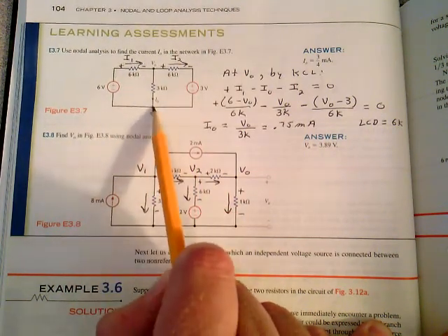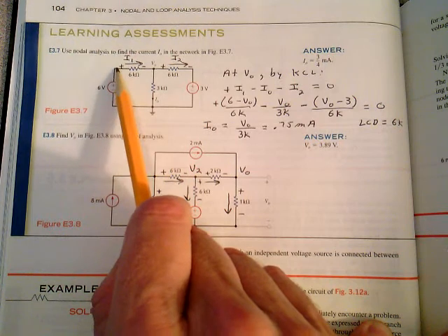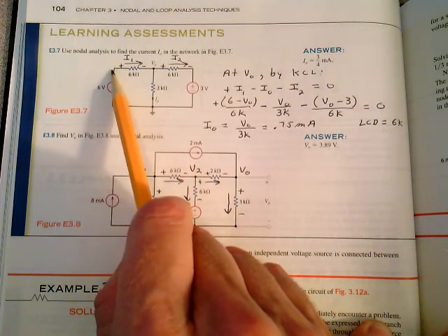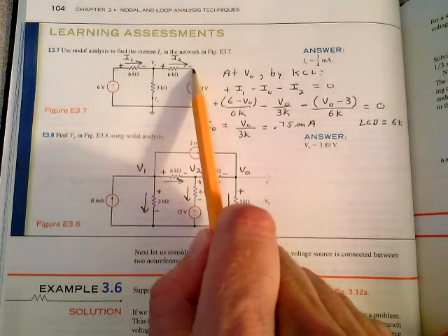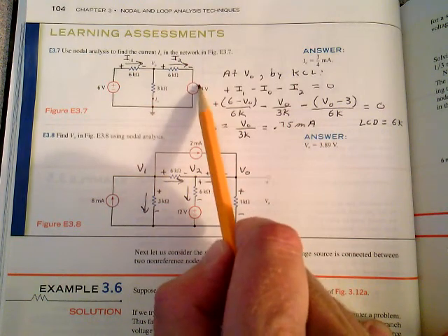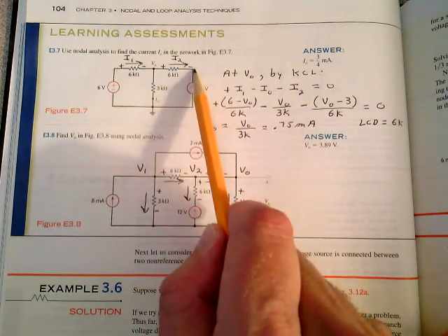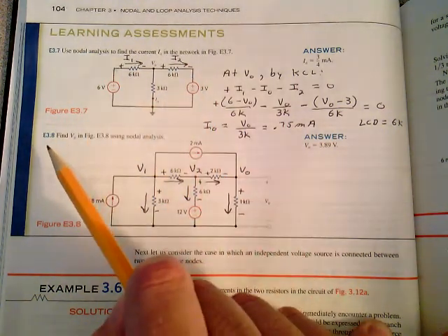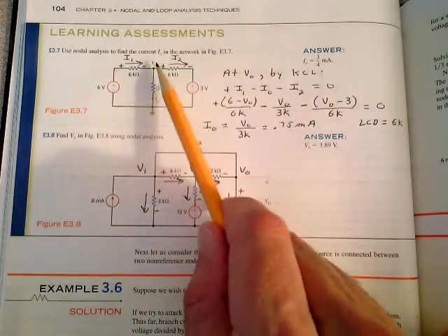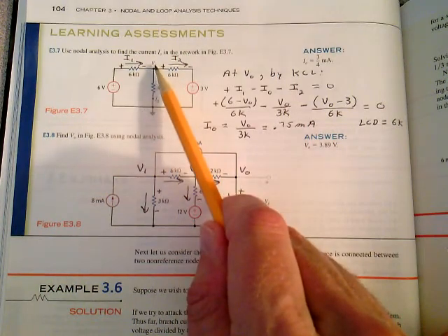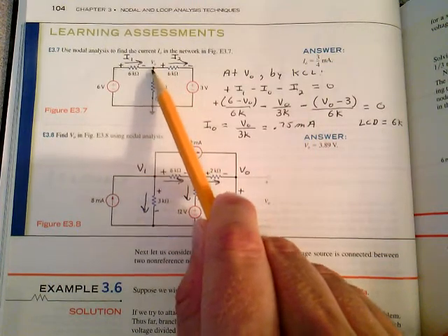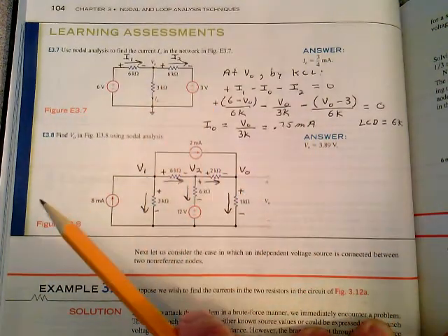If this is ground and you're up 6 volts, that's 6 volts right there. You already know that point. So that's not a node we need to write an equation at. Same thing over here. If this is ground and you're up 3 volts, you're plus 3. Now if this is turned around, this would be minus 3 up here. But it's plus 3. So at node V0 by Kirchhoff's, there's two nodes and one's a reference. So right there, you just need one equation. And there's your equation right there. There's the current equation at that point when I assign the currents.